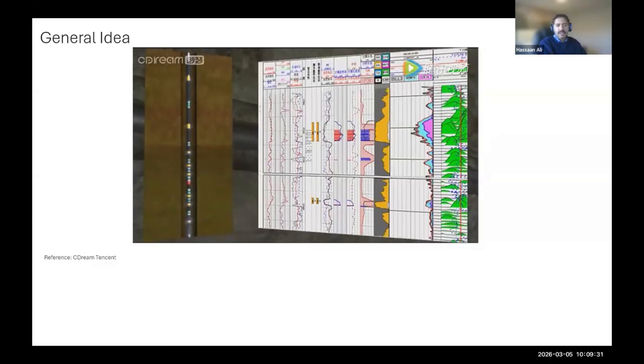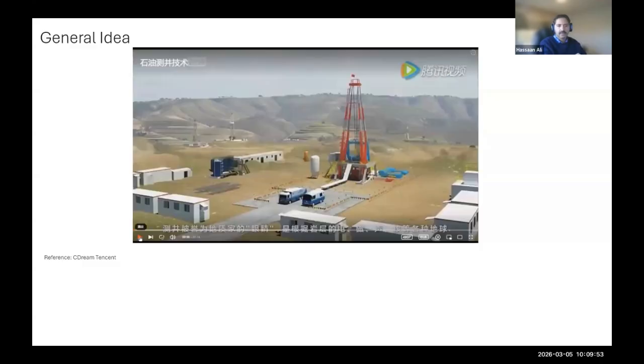All right, so now it should give you an idea of what we are talking about. What is wireline? This tool string that you see right over here is essentially a big array of sensors, and it is lowered into the wellbore using an electric cable. And from that electric cable, this technology gets its name, wireline.